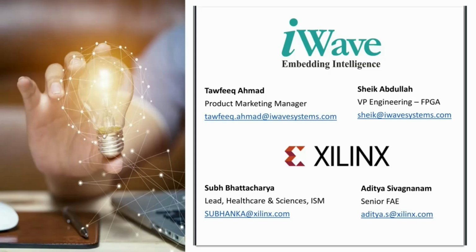So our standard development kit supports 12G SDI input and output, and HDMI 2.0 input and output on the development kit. And we have two FMC connectors. So there are many off-the-shelf FMC modules available for MIPI cameras and other video interfaces. By using that, we can support other cameras like USB, Ethernet, LiDAR, MIPI cameras, SDI cameras. So all sorts of cameras can be supported using our SOM-based development kit.